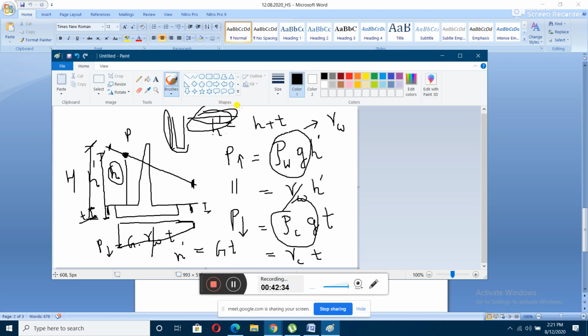He just used a uniform value. That's why you have multiplied it by 2 times that of d1. That value you have multiplied. But it is not the case. There is a distinction between the flow of water, horizontal and vertical is not same. So everybody knows that the vertical flow of water is more than that of horizontal flow of water, right? So he did not distinguish between the horizontal and vertical creep, that should be there. That is one limitation.